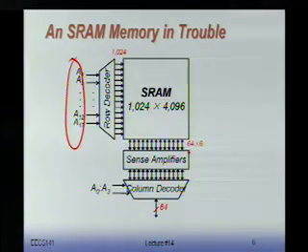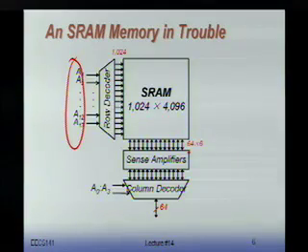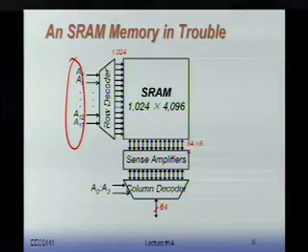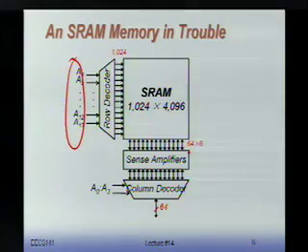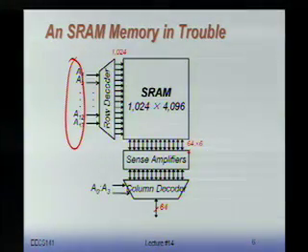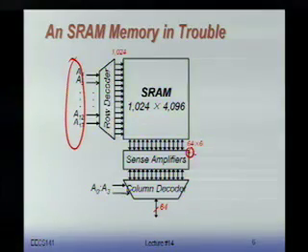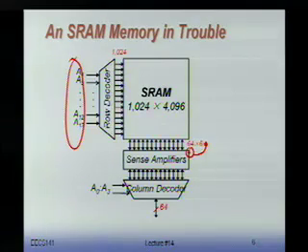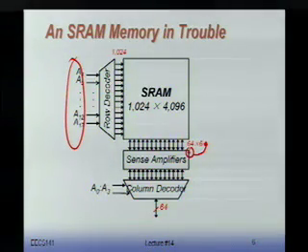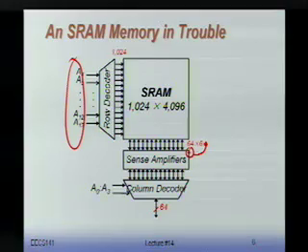Now, in this project, we like to have the data stored as chunks of 64 bits. Let's say this is for a 64-bit processor. They're stored in 64 bits, but you don't want a very long, skinny 64-bit memory, let's say 16,000 or even a lot more. So we put a number of the 64-bit words together in one single row. Actually, this is not correct, this 4 should be right here. It's actually 64 by 64, which makes exactly 4,096. So in every row, I have 64 of those words stored.